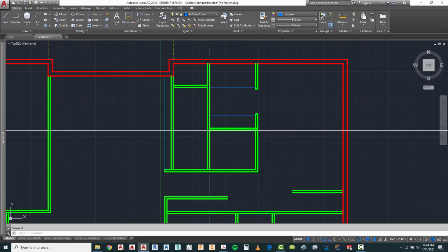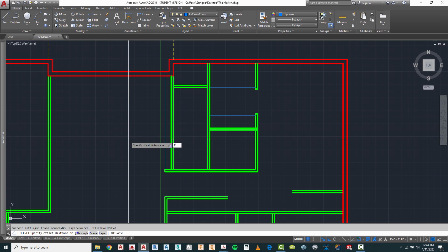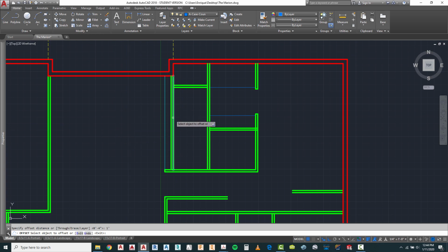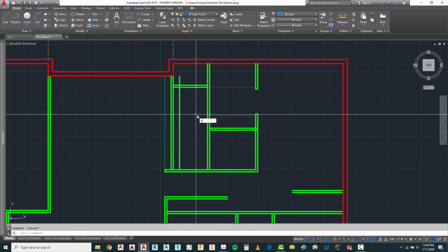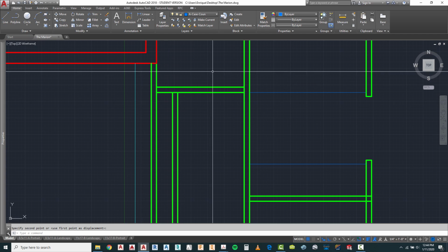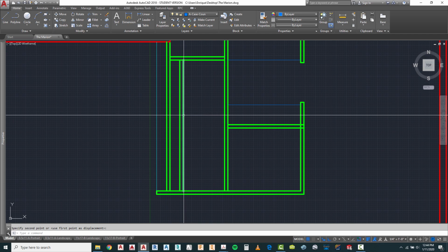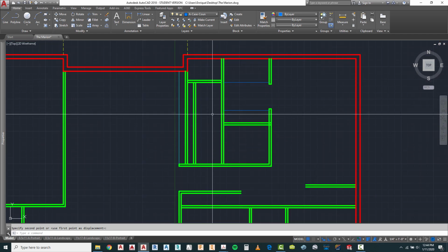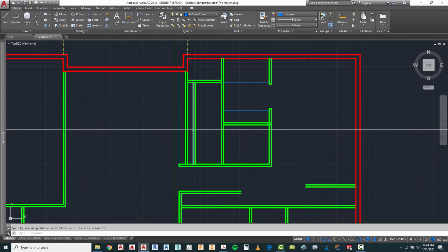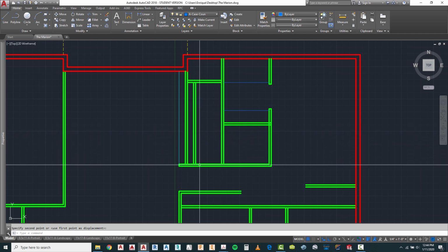So we can go back to our drawing. I'm going to take this line right in here, use the offset command at 1 foot, and click that there, offset 4 inches. I'm going to clean this up just a little bit. I'm going to use a stretch crossing selection and trim that out later, and that is where we have that located right there. Now let's see what we can do. We can set up our walls in here for our fireplace, which may have some effect on how we lay out our bathroom in here.